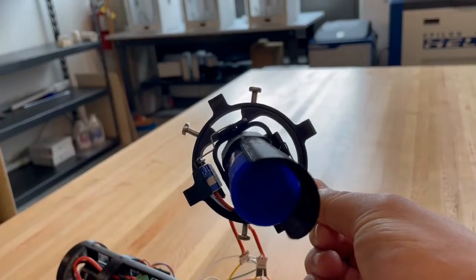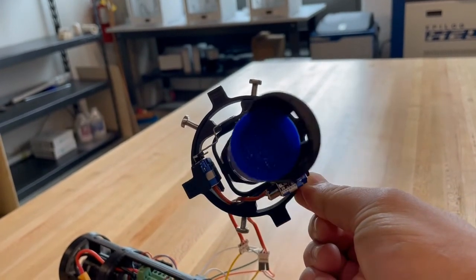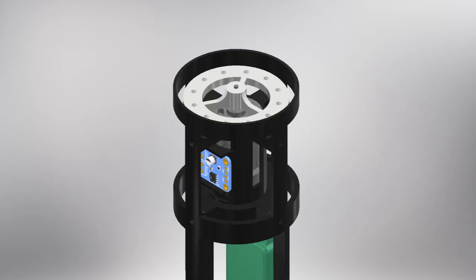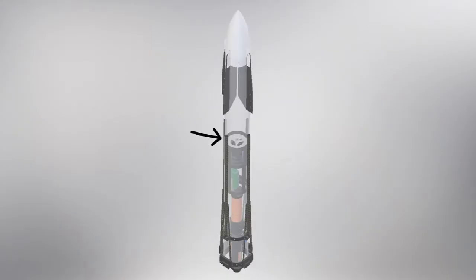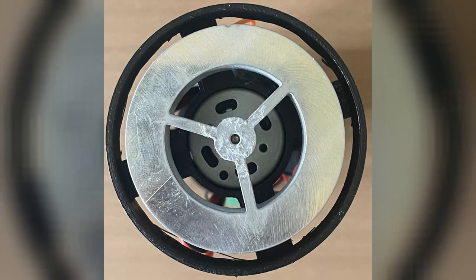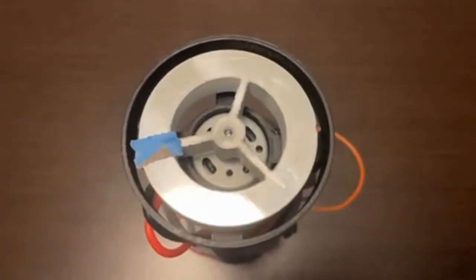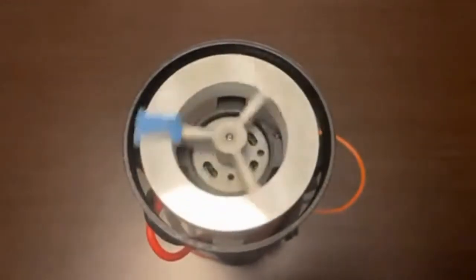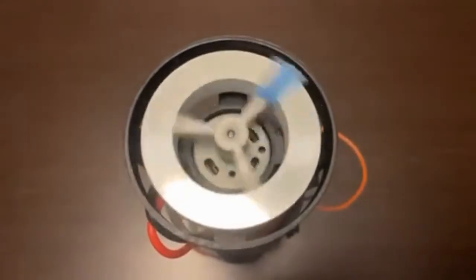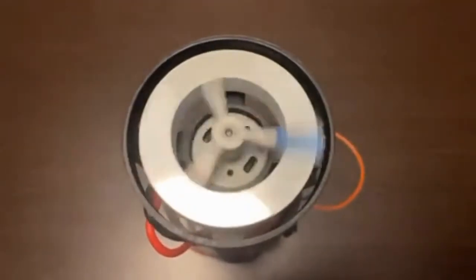Two high-accuracy digital servos were used to control the two axes of the gimbal. The control system is able to create torques that rotate the rocket around its x and z axes by vectoring the thrust. To control the roll axis, a reaction wheel was constructed and placed near the center of mass in the rocket airframe. Aluminum was used for the construction of the wheel as it has a high mass moment of inertia, providing greater control. A 12-volt brushed DC motor was used to spin the reaction wheel, as unlike the brushless variety, brushed motors have a less aggressive stop when polarity is reversed.